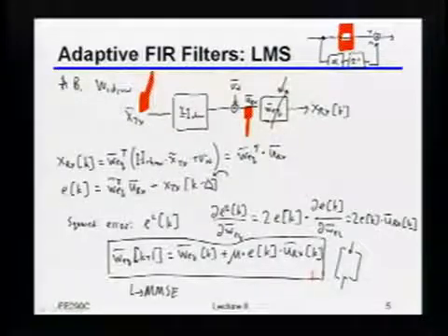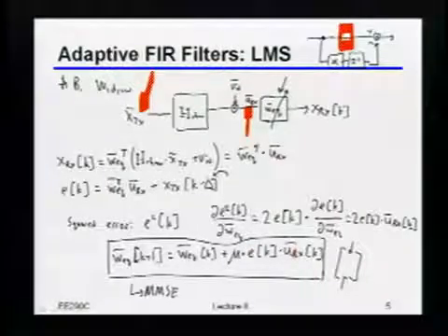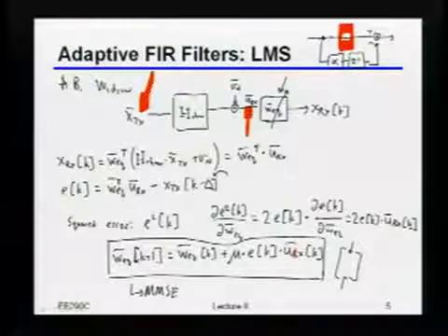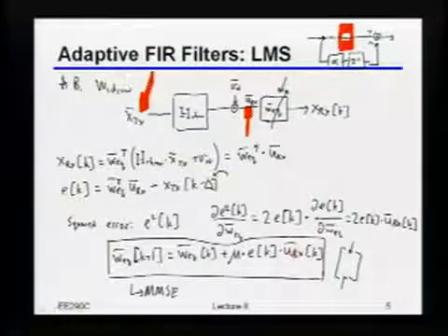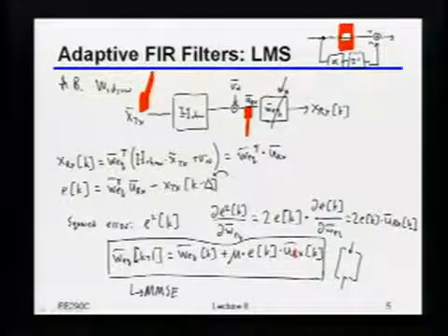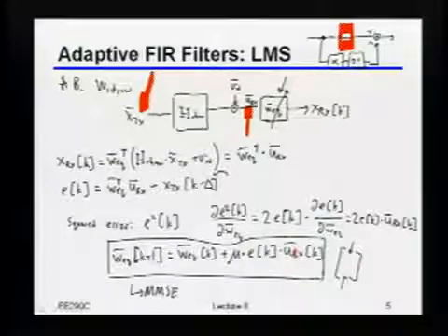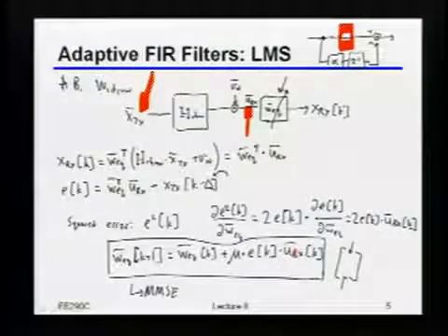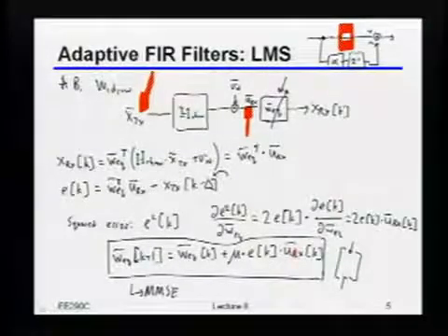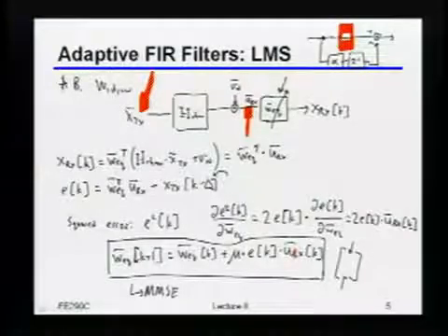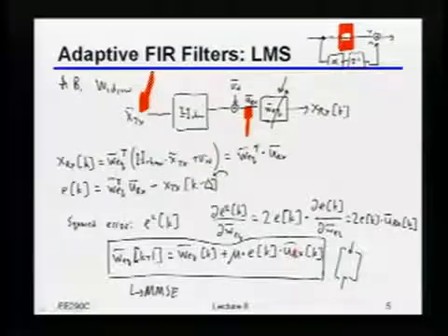Because as long as things are uncorrelated, when you do this multiply and average operation over time, you'll actually get the right answer. Does that make sense to people? When you can guarantee that the quantization error is uncorrelated is a little bit of fun, but take my word for it, that does tend to work out for most or almost all practical channels that I've ever seen.